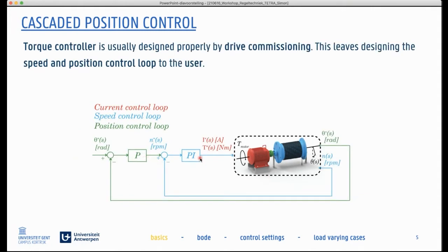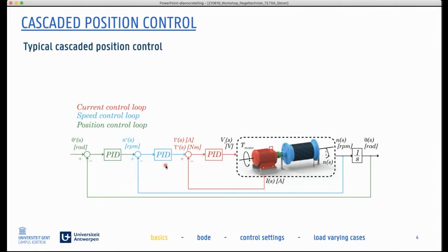You have the error signal on the speed, and then you can use a PI controller to dictate the desired current or the desired torque in the motor, because the larger the deviation is between the required speed and the actual speed, the more force and the more energy, the more torque you will need to put in the motor to accelerate to obtain that position.